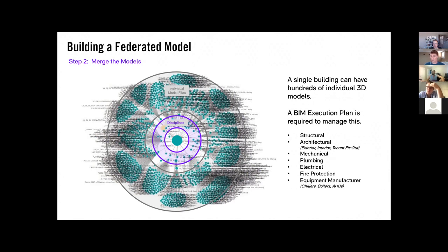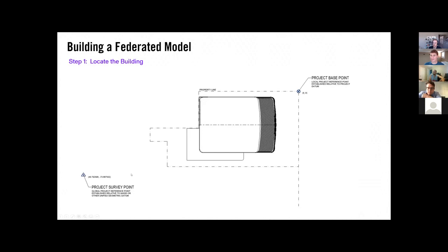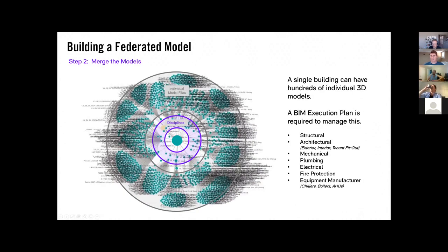They're all relating to this common base point, most importantly, if you're trying to do something with the 3D geometry. And there's kind of a quality behind this. If the mechanical design is expected to be used for the operations of the building within a digital twin, you need to specify that certain objects do get modeled and that they have the right properties within them so you can use them later on.